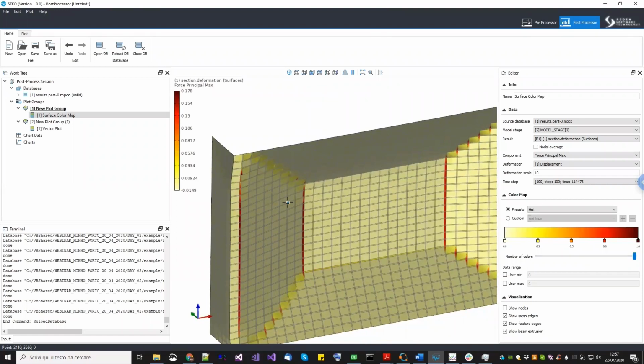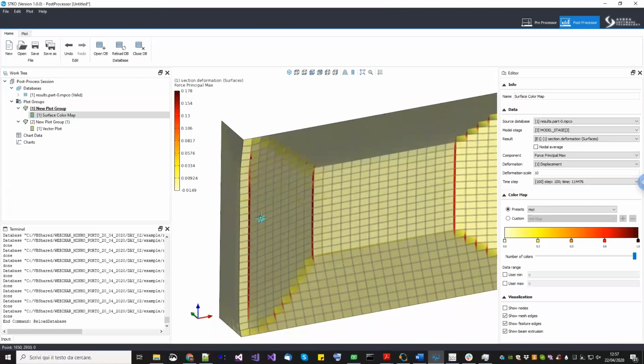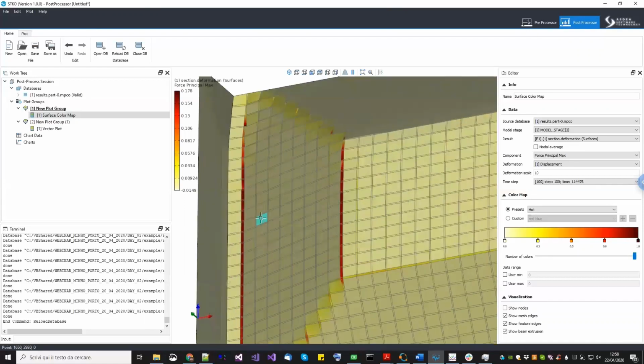The only problem is how the finite element is sending the strain to the material. The finite element, in this case, since it is a thin shell, assumes that the out-of-plane shear deformations are negligible. Since they are assumed negligible, it directly sends 0 to the material as a transverse shear. And of course, the material does not receive any transverse shear, and this transverse shear will not create any damage in the material. But as you have seen before, the transverse shear in this kind of example is much higher than the other strains. So that's why here the mortar joint is not failing as before.